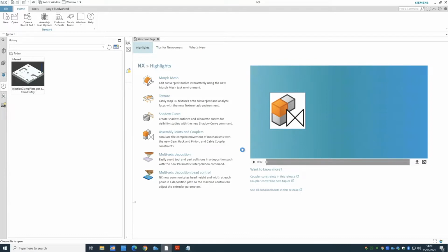It might take some time because it's opening and converting at the same time. I would recommend you do it at the same time with me. Once you've downloaded the file, put it into a folder, then locate it through NX, open it, and wait for it to convert to the .prt file that is compatible with NX.